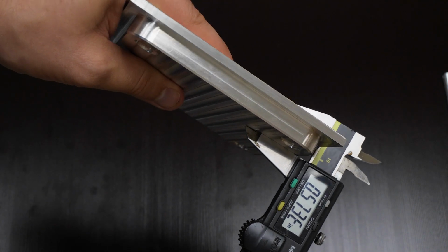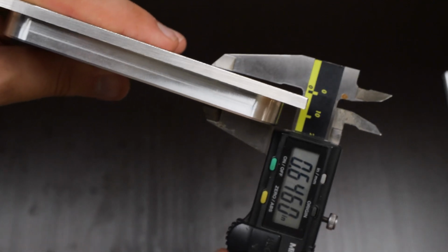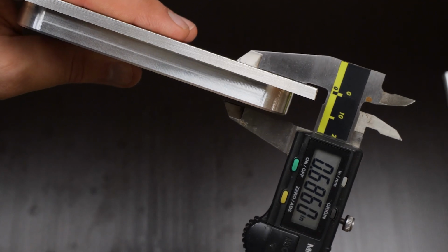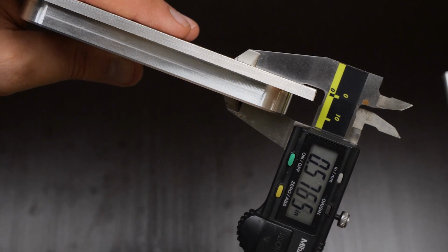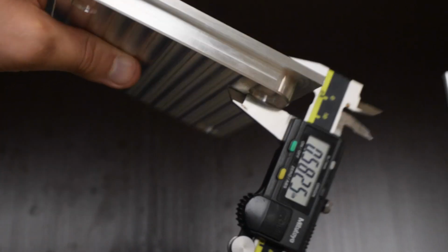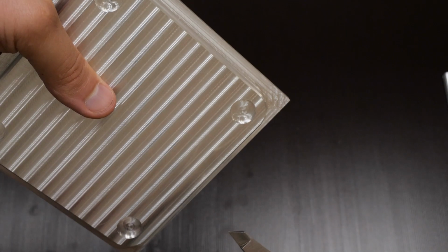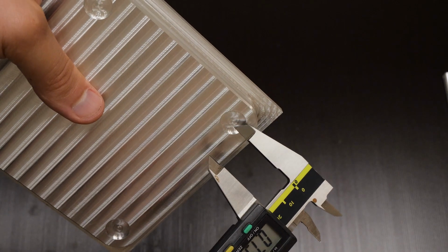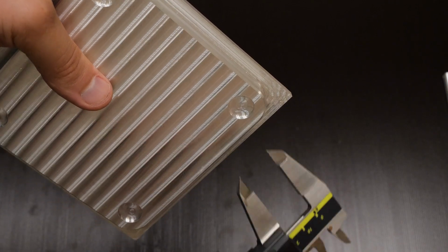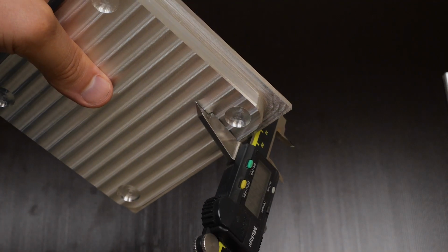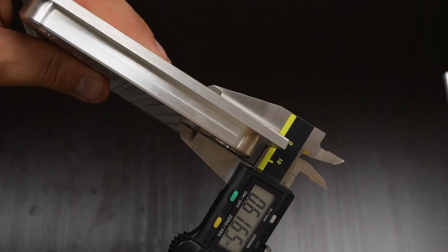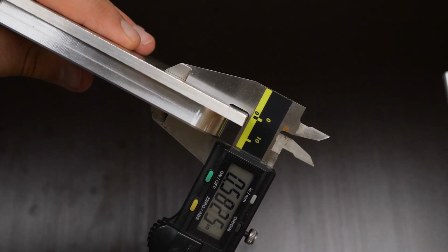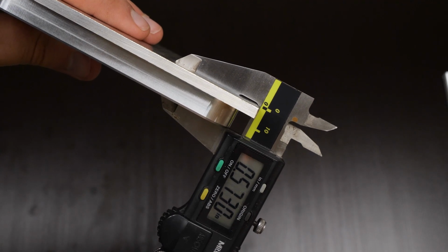Now, as I'm measuring with these calipers, just in case not everyone knows exactly what I'm doing here, I'll explain how I'm holding my calipers a little bit. What I'm trying to do on the back side is use that little space in the calipers to avoid the burr on the back side. Another thing I'm trying to do is avoid any burrs that might be in these circular pockets. So I'm holding my jaws just under those pockets. And again, I'm using that space in the back of the calipers to avoid any burrs that might be on my stock material. And I'm getting it nice and snug down in there until I get a good solid reading.